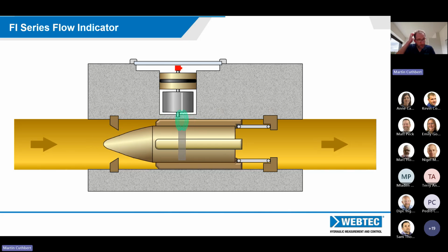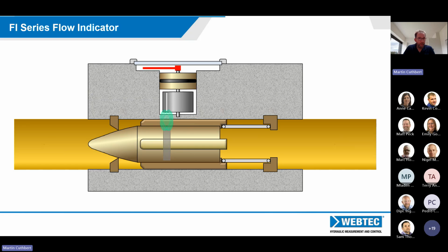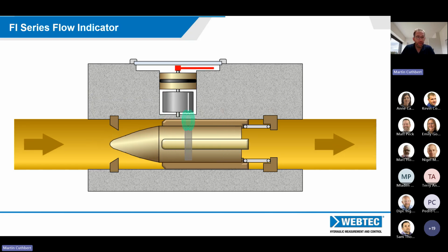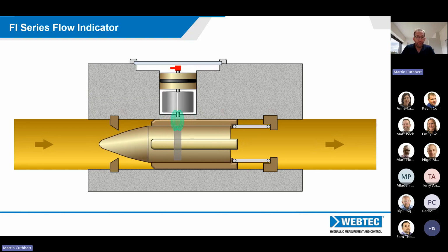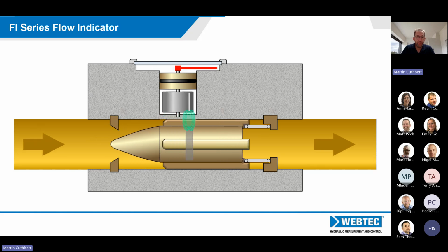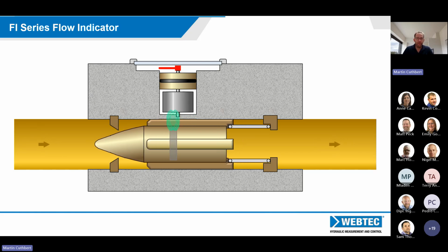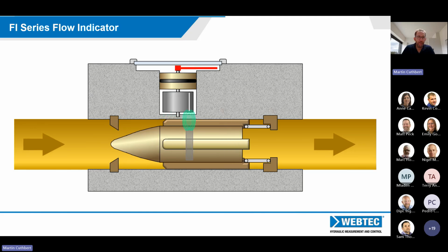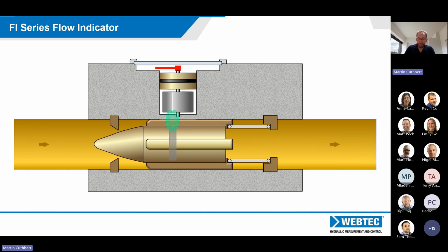These particular units are installed in the pressure line, allowing you to measure at high pressure what the flow is out of the pump, which is the first place really to focus on if anything's moving slowly. If cylinders or motors are moving slowly within the application, then that would be the starting place to check the pump is delivering the correct flow.